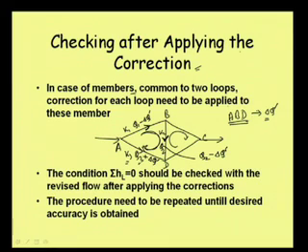That means, in an easier way, you can also say that if the delta q correction is positive, we are applying minus delta q. That means we are considering delta q flowing in the opposite direction. So when it is facing delta q in the opposite direction, the flow will become q2 minus delta q. Here it is q1 minus delta q, but here it is in the direction of the flow. The correction we are giving is in the opposite direction because it is minus delta q, as we considered in the start itself. So it is q3 plus delta q.